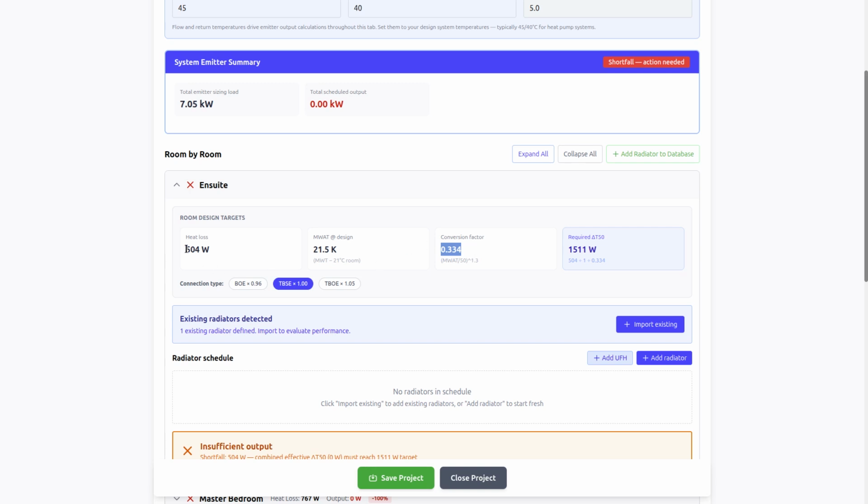So with this mean water to air temperature difference, the radiator we are going to choose has to be able to put out approximately 3 times as much heat at the industry standard test measures. This is why people talk about how heat pumps have to have bigger radiators.